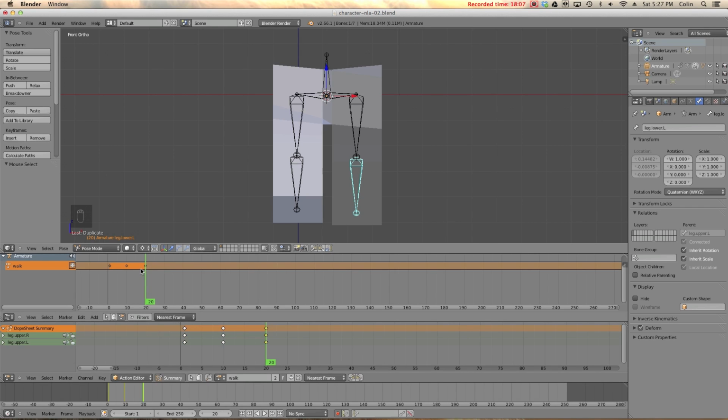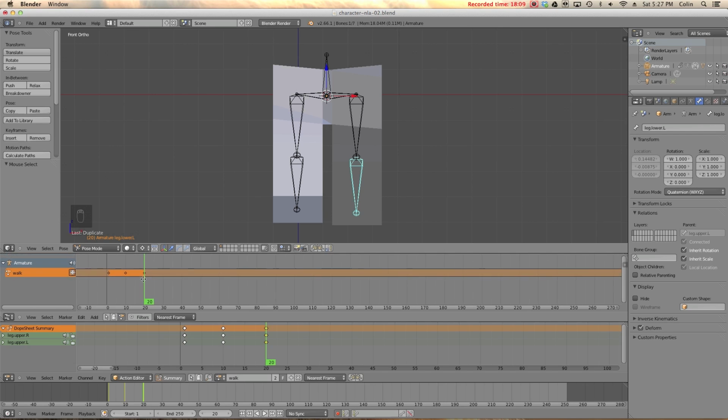And that's because we're not really supposed to be able to do that in the NLA Editor window. What we want to do in here is actually take this animation and convert it into a block of data that we can manipulate and combine with other blocks of animation data, like the splits animation that we just created. To make this animation, in other words these keyframes, into a block of data in the NLA Editor window, we have to click on this snowflake.